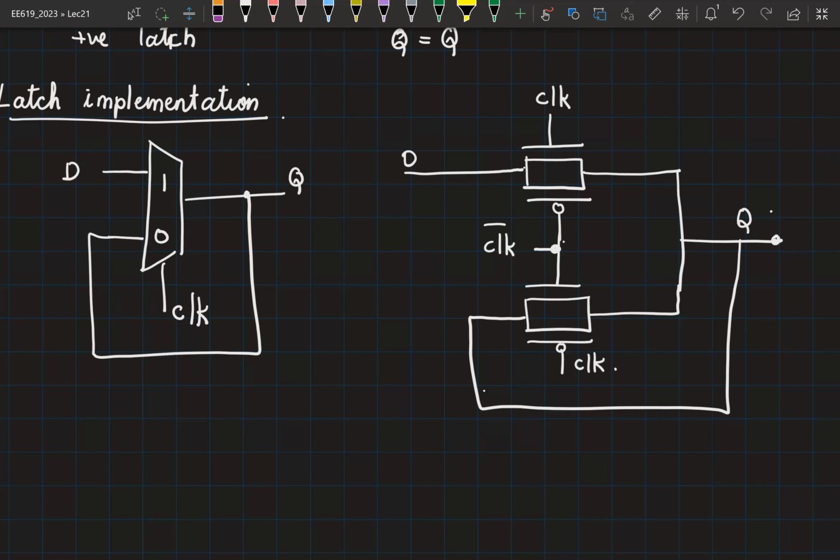So what happens is, for all the other implementations, you know what is the input capacitance that you are offering, right? And you know what is the drive strength that is available to you. The only missing information is basically the rise time of the signal at the input, correct? So usually you would make a table, any standard cell you design, any basic module you design, you will have a table for the delay. And the table will have two variable parameters. One is the rise and fall time of the signal being applied. The other is the total load capacitance at the output.